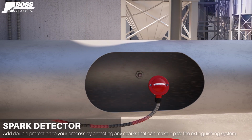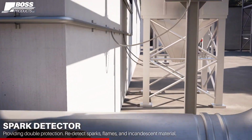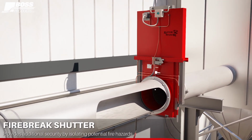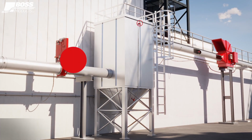We can also do redetect. I've done a lot of applications where sometimes they want to be safer than sorry, and we can do detect, extinguish, redetect, and then possibly put a mechanical fire break shutter as close to the vessel as possible. And basically what happens is it's a knife gate and it triggers and shuts that duct down.